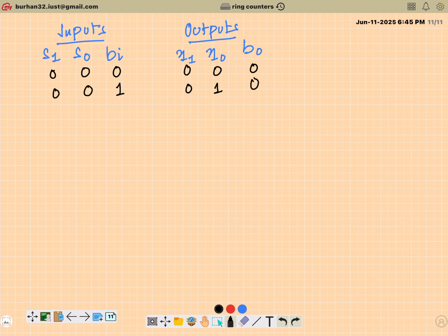Fine. But when I am in state 01, first my output will be 1 in this state. Then if I don't press the button, if I release the button, I will come back to the state 00. If I am in the state 01, but I continue to press the button, my output will be 1 because it is defined by the current state, which is 01.